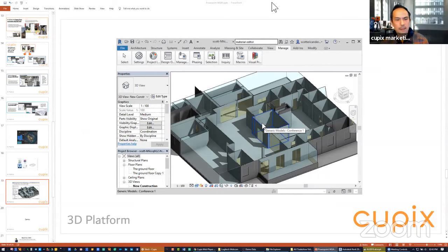Let's say you're looking at doors. If you're trying to resolve whether it's a 40-inch door, a 36-inch door, or a 32-inch door, that's absolutely doable. Point taken. But it ties into the tolerances of the trade. If some trade is installing glass and the tolerances for installing glass are really tight, then he or she's probably going to want to go out there and measure it themselves.